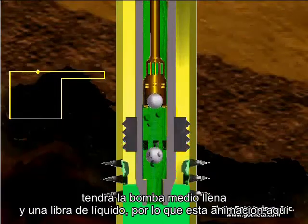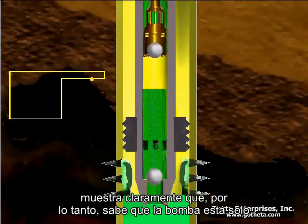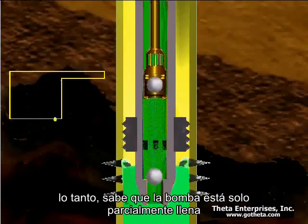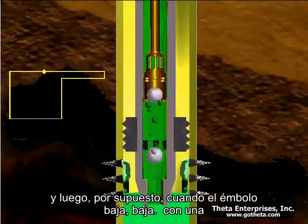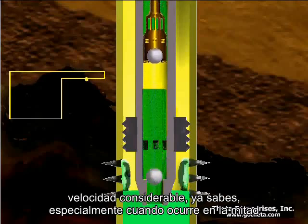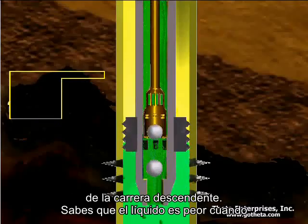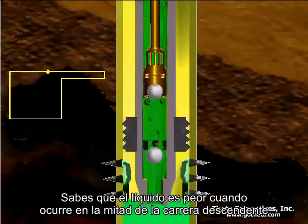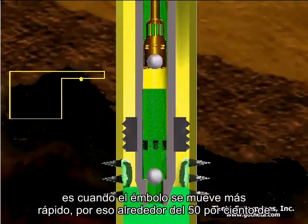This animation clearly shows that. Therefore, the pump is only partially full. And then, of course, when the plunger comes down, it comes down with considerable speed, especially when it happens in the middle of the downstroke. Fluid pound is worse when it happens in the middle of the downstroke because that's when the plunger is moving the fastest.